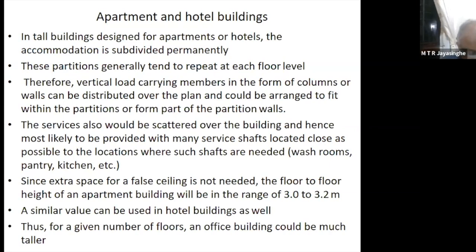One is on concrete technology, other one is on slabs, other one is using systems other than reinforced concrete like PT and precast beam slab systems. And also I showed you why high strength concrete can be so important when it comes to tall buildings, because stiffness can be increased by using high strength concrete.